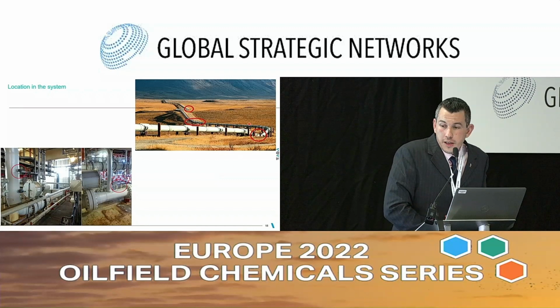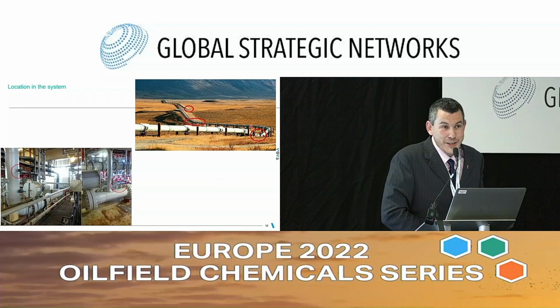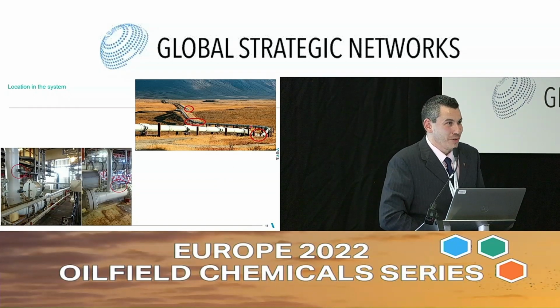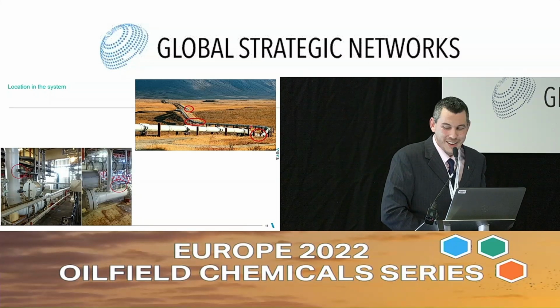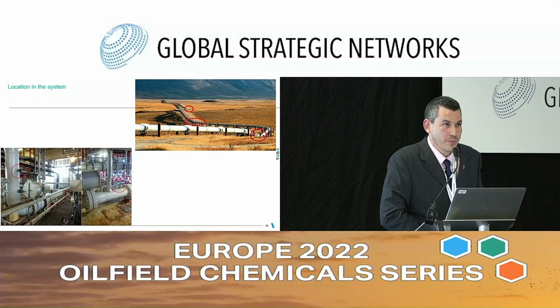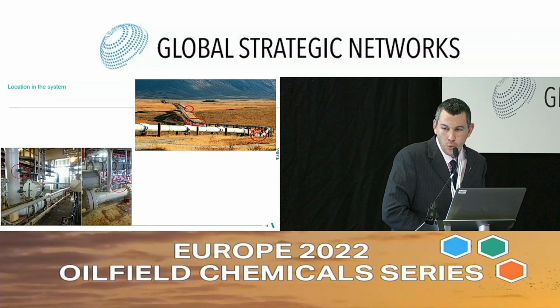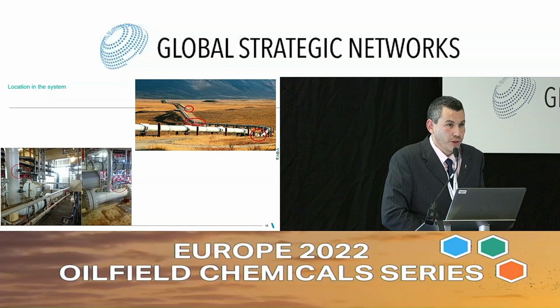This is a nice picture. Here, I think we don't need any mathematical model to predict where we might have water accumulation. Of course, in the lowest spots of the pipelines, most likely you will have water accumulation. And if possible, try to install access fittings in this area.